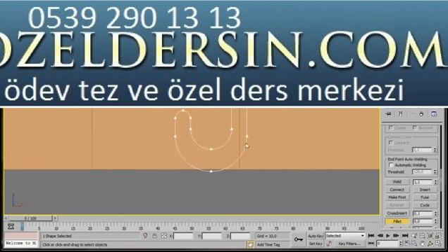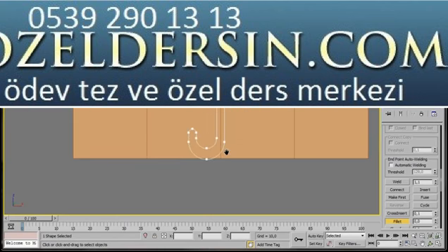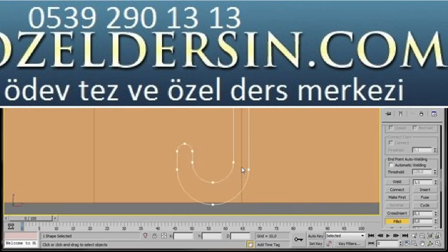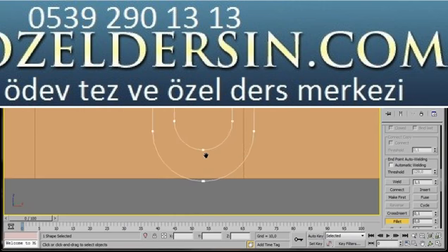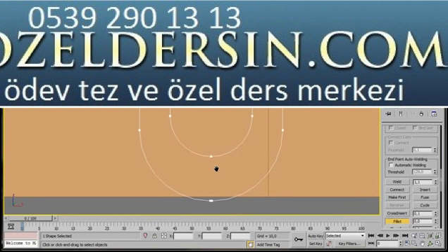There we are. That's not bad, but if we like, we can just do a few more tweaks. I'll just zoom in a wee bit. Depending on what your shape looks like, you might like to weld a few more vertices. Well, what I'm going to do is select my segment mode. I'm going to select this segment, hold the Control key down and select the next segment and just drag it down. There we are. I think that's fine there.